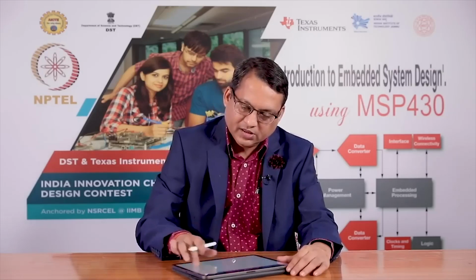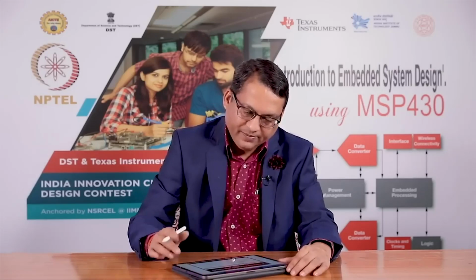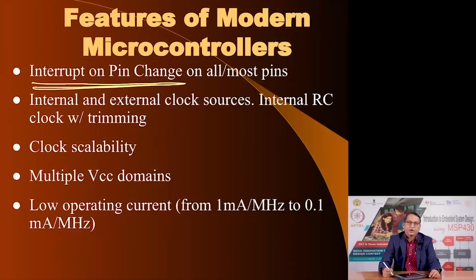Let us see another, go to the next slide. Now, on modern microcontrollers, you do not have to worry about the limited number of pins with the interrupt capability, because now most of these microcontrollers offer almost all the pins with a feature called interrupt on pin change.